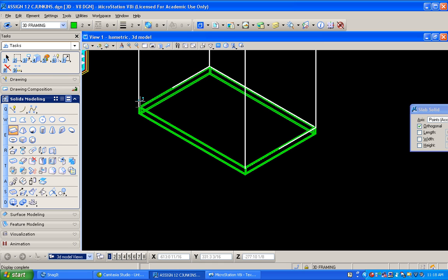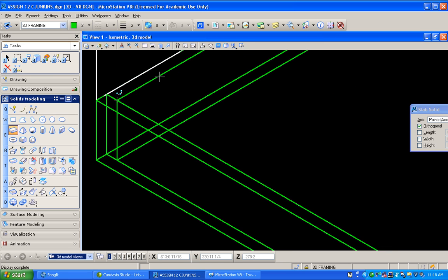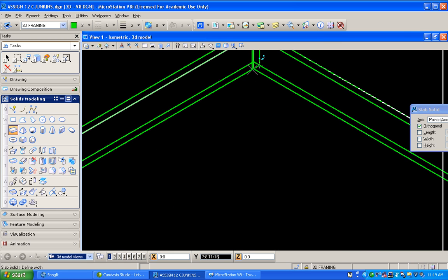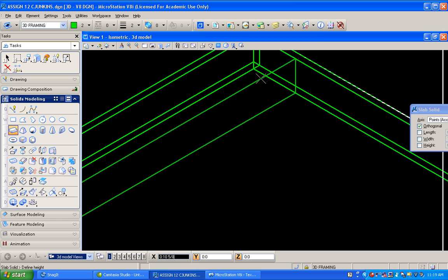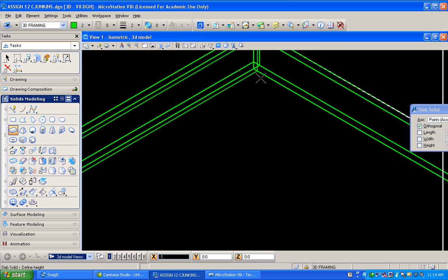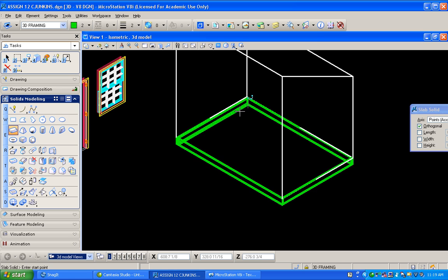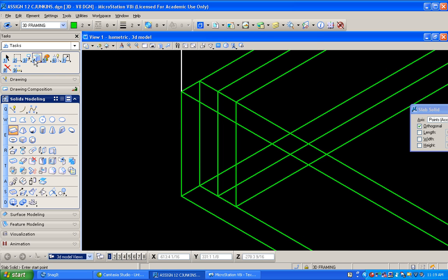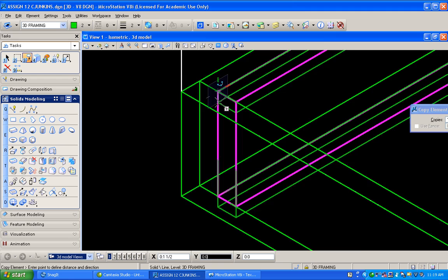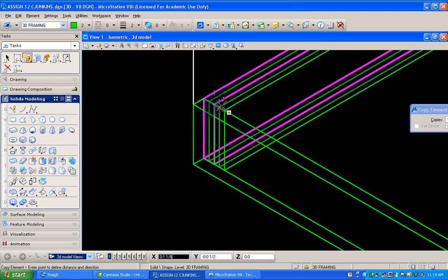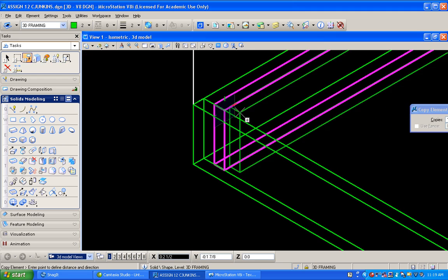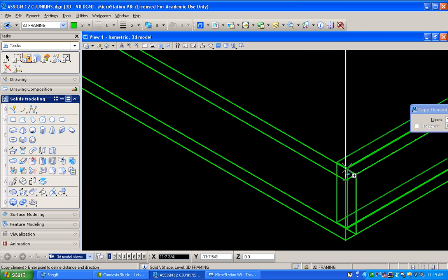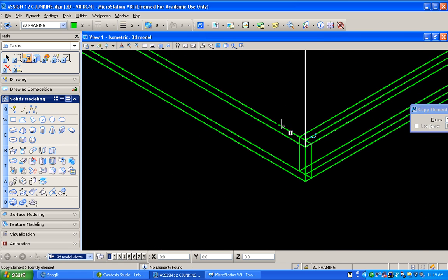another one. We're going to double band the framing on this, so we're actually going to just trace the inside of this one. If I just go here to here, come over, well, I guess it's already in the front, come over here to this intersection, and then just come out colon 1.5. And then we can take that one and copy it. Whoops, got to grab it by the other handle here. This handle. Copy it down to this end. Place it right there.